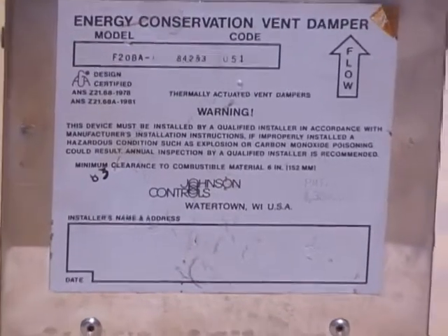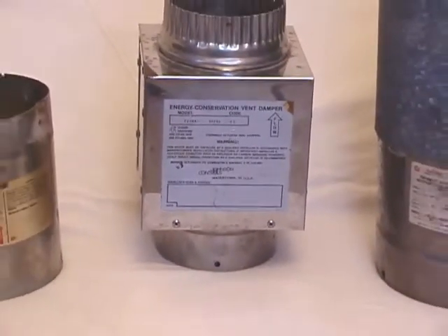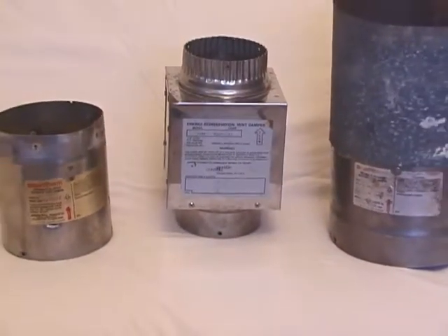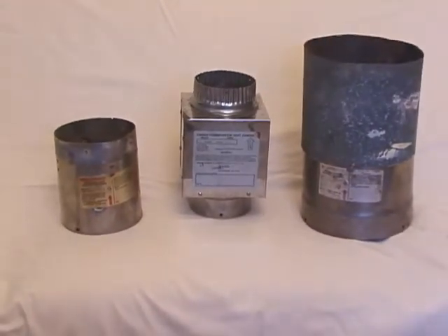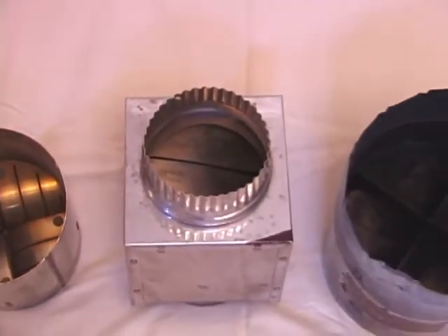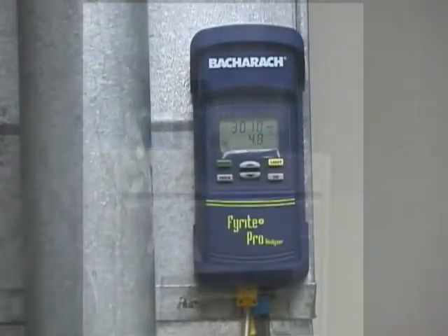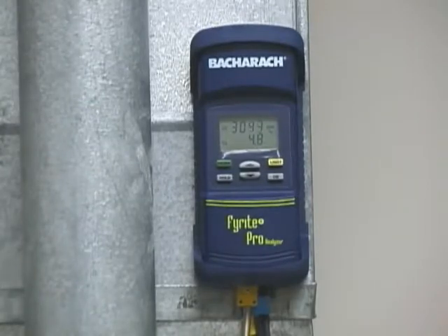For this reason, we at Comfort Institute discourage the use of mechanical vent dampers in that they tend to increase the amount and length of time of spillage at startup. This is because they are closed and blocking the vent until they warm up adequately. Electronic dampers, on the other hand, must open prior to the gas valve opening, so they do not contribute to spillage at startup. Spillage has the potential to create very high levels of carbon monoxide.